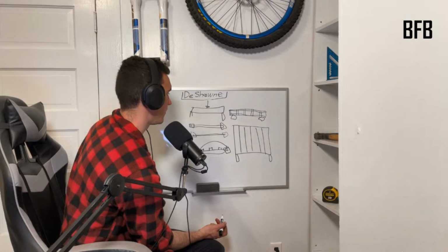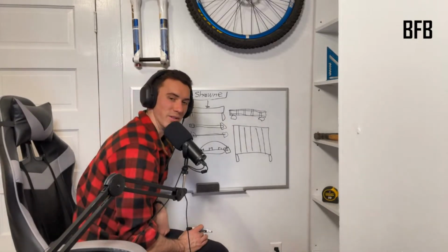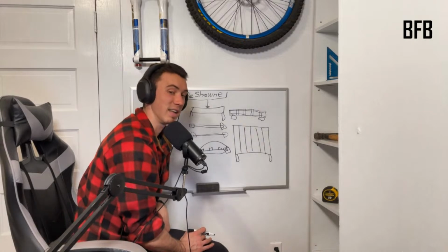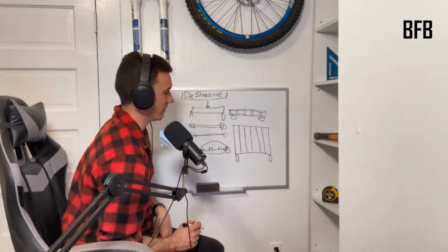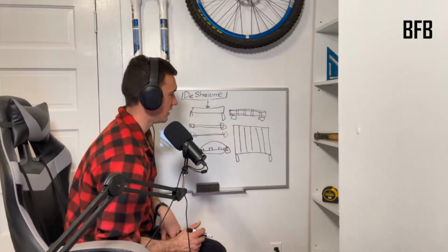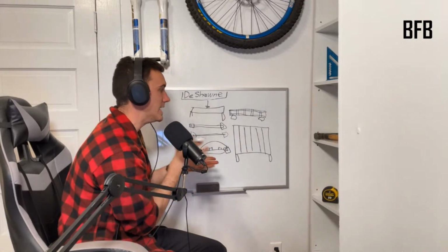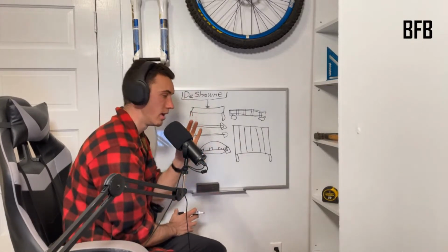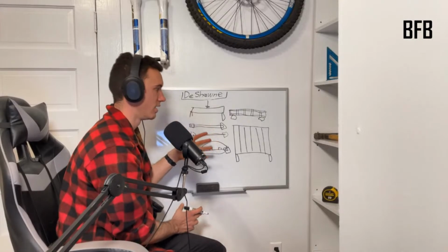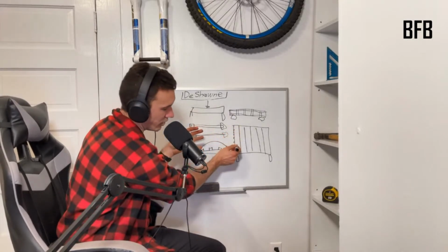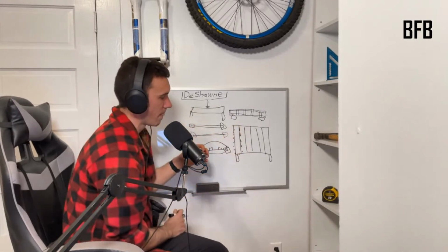You know what we just made? I bet you know what we just made. We just made a ceiling diaphragm right there. That's all it is. It's a flat, deep, thin, blocked, nailed beam.